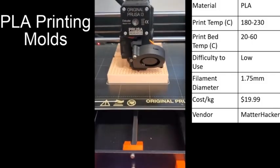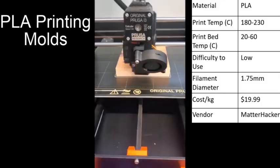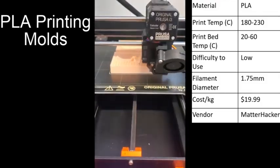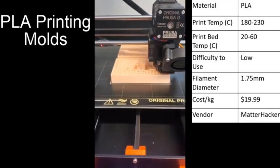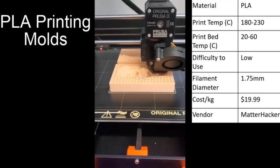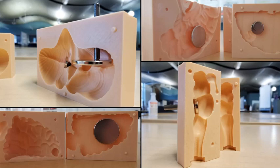The best identified method to create the brain model is using the molding process. PLA plastic was the chosen material to 3D print our molds because of its cheap cost, versatility, and ease of removing the model from the mold. Magnets are being used as a latching mechanism to hold the model together and allow for the simulation of the dissection process. Metal dowel pins were inserted into specified locations in the molds for proper magnet positioning.